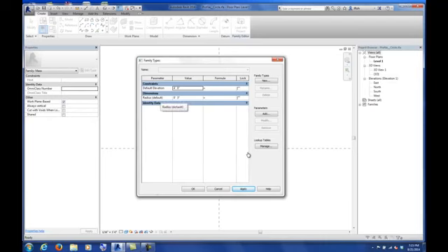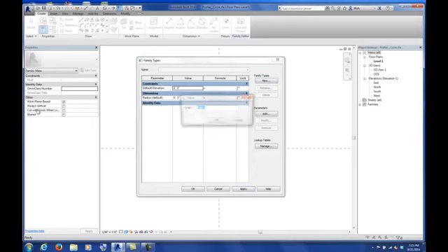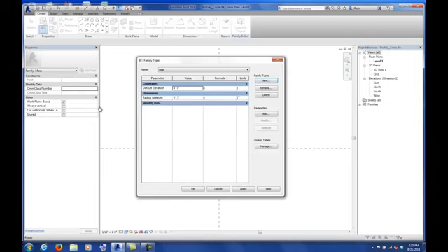The instance parameter can be whatever dimension we want as we place it in another file. So telling it that it was a 6-inch diameter or a 3-inch doesn't make any sense, because essentially we could make it any dimension we want. So I could actually just click on where it says family types and new. I'm just going to call this pipe instead, because it's going to be any kind of pipe that we want it to be. I'm going to click OK.